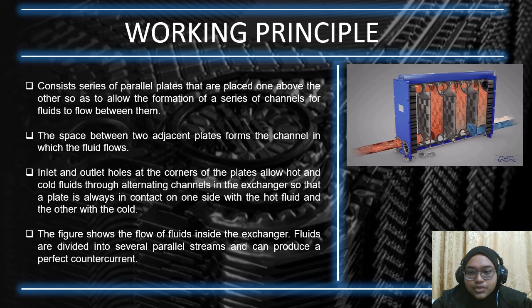The figure on the right side of my slide shows the flow of fluids inside the exchanger. The fluid is divided into several parallel streams and can produce a perfect countercurrent. This is because of the gasket and the channels, so the cold water and the hot water streams won't mix together.